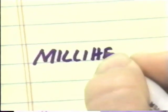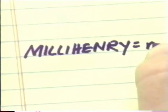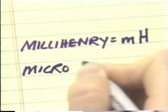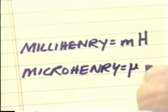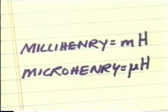For many practical applications, two smaller units are employed. One is the millihenry, abbreviated with a lowercase m and a capital H. A millihenry equals 1/1,000th of a henry. The other is the microhenry, abbreviated mu capital H. A microhenry is equal to 1/1,000,000th of a henry.